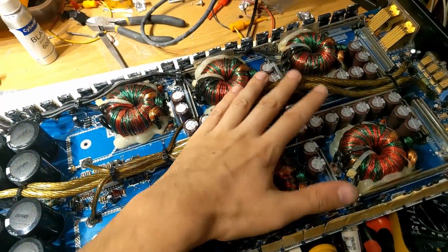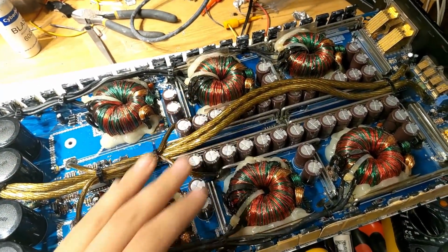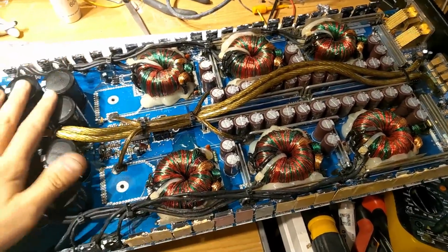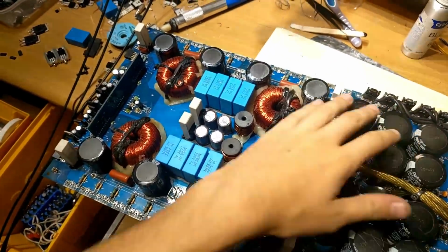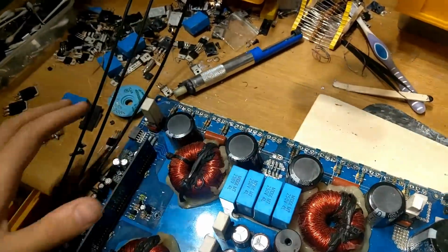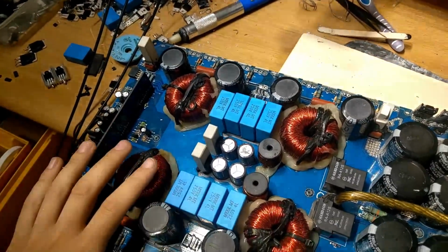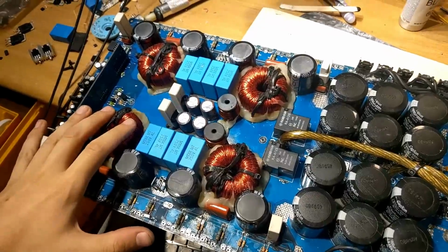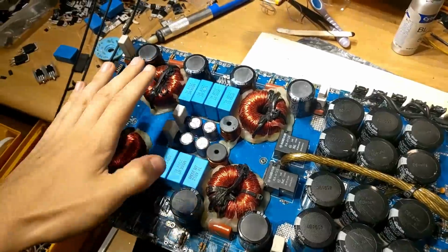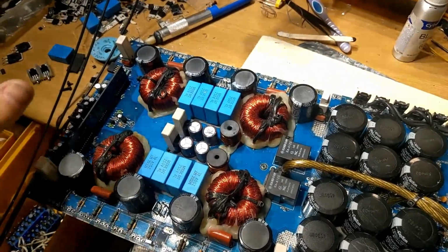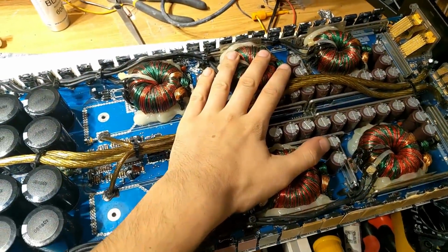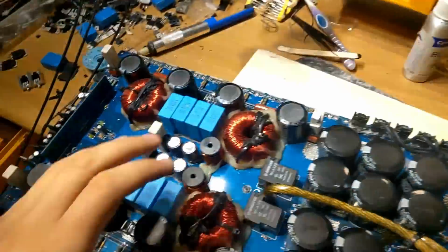Luckily the power supply section was intact. If that had failed as well, that would have been a very expensive repair, but luckily the output section was not damaged. The customer was very sensible actually. When this amplifier failed, he heard a massive pop from this area over here where the FETs exploded and completely obliterated, and he did not power the amplifier back on again after it went into protection after hearing the loud pop. That is a good customer. The best thing is not to try and power the amplifier back up again. If you heard a big pop and it's gone into protection, do not try and power the amplifier back up, because you will kill the power supply section. So yeah, awesome stuff. That should be good to go today.